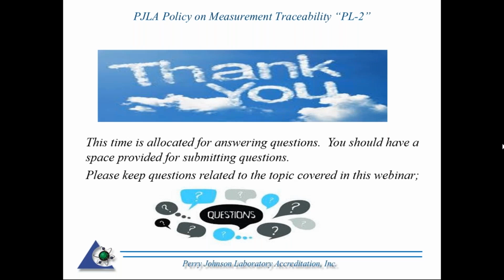What I can say as far as any sort of measurement uncertainty, you always have three elements in there. You have the uncertainty associated with the standard. So if it's temperature, you have a thermometer, a standard that you're using, that comes off the report, and then you start building on that. So typically, on any type of uncertainty budget, no matter what it is, you have uncertainty contributors: uncertainty of the standard, uncertainty of the limited resolution of the device under test.